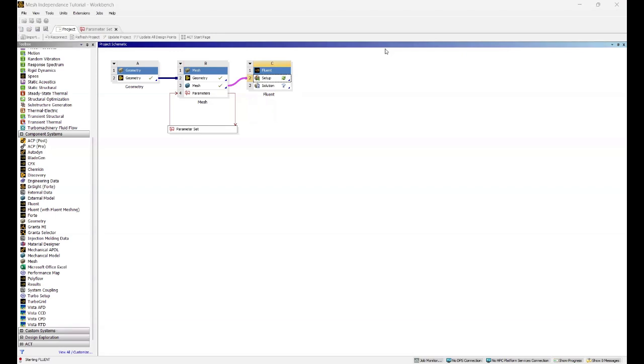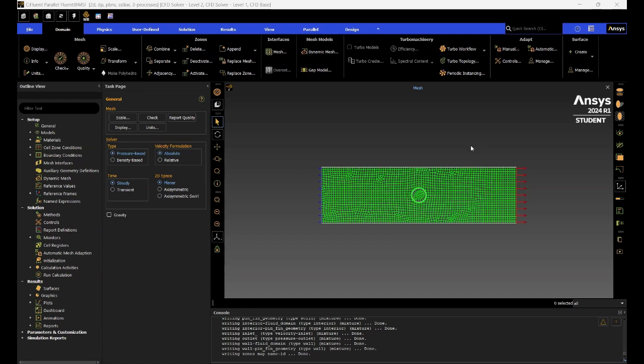What I like to do is, when it shows the Fluent launcher, I don't know if you can see this on my end or on your end, but I like to do double precision. And I just like to do 3 cores on the process because it depends on your computer. If you have 24 cores, you could activate all 24 cores to run the simulation faster. But for me, I just like to do 3 cores. See, the Fluent simulation is open now.